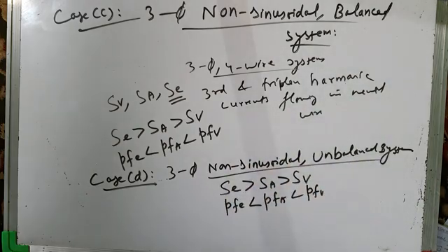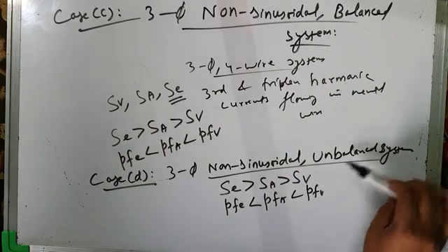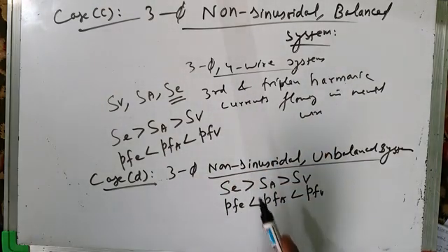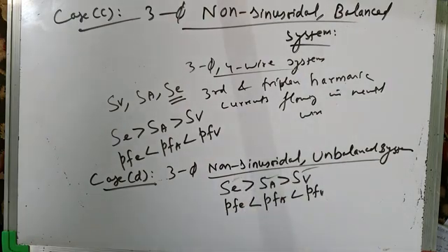Because of the non-sinusoidal source, there will be neutral current. Because of unbalance in the system, it will cause increased neutral current, and it will also cause additional feeder losses, which are taken care of by these types of apparent powers. Then the three-phase, three-wire system was also discussed, and there also we calculated these types of apparent powers. The analysis done by us in the last lecture was aided by a couple of numerical problems which we tried to solve in today's lecture. In fact, this is the worst type of power quality problem.